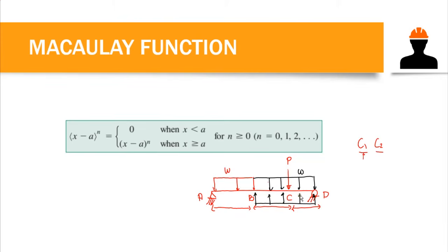If we have a unit load w here, and then we introduce another w load below, then there would be balance in our beam, as if we did not introduce another load. That's the purpose of having the same load acting in the opposite direction. In that case, we can just cut our beam at this point. So cutting at only one section gives us the answer for the deflection at any point in that beam without having any trouble in evaluating the functions.